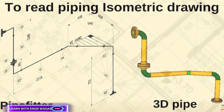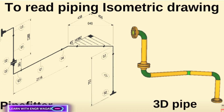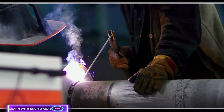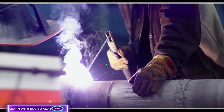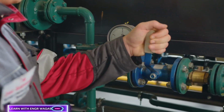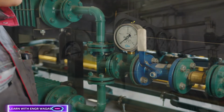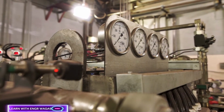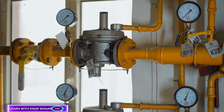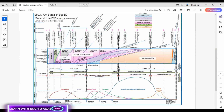And then isometric drawings actually provide a 3D view of individual piping sections, detailing the piping dimensions, orientations, and connection points, obviously having a vital role in the fabrication and installation for the people who are going to fabricate them. So then there is a pipe stress analysis report. This stress analysis ensures that the piping system can handle internal pressure. Pressure is a very important factor. Thermal expansion, obviously, because hydrocarbons or whatever the fluid is going through that piping, that is going to be very important. And external forces.